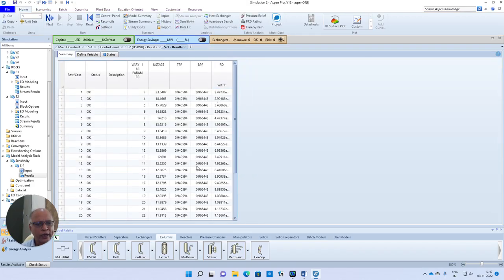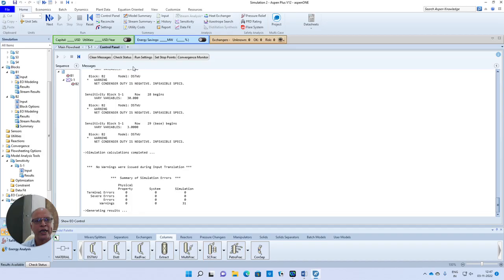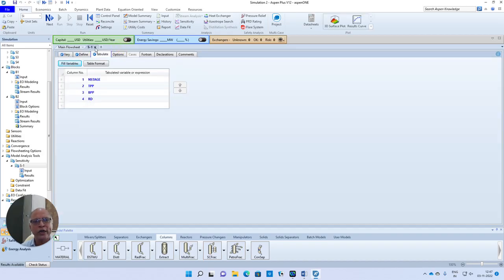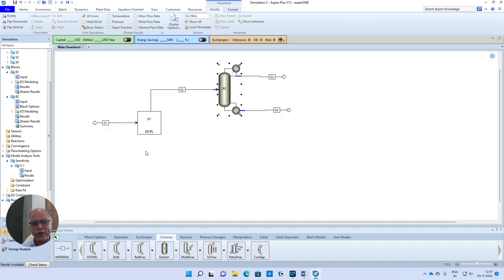So we were able to get a purity of 94% and 96% with respect to propane and isobutane, respectively, in the top product as well as the bottom product. I don't want to fine tune this design because this itself is a shortcut design model. Now I will try to do that fine tuning in the other model, this being very